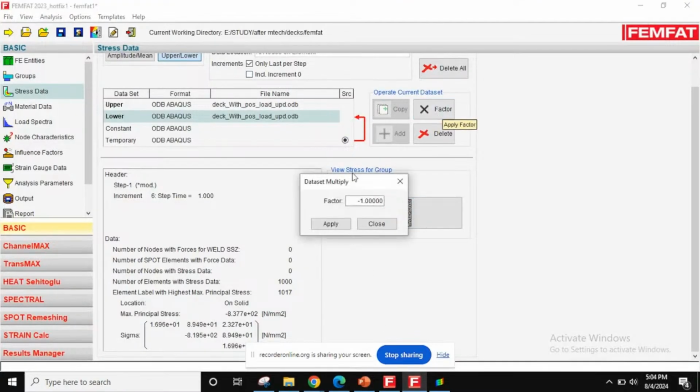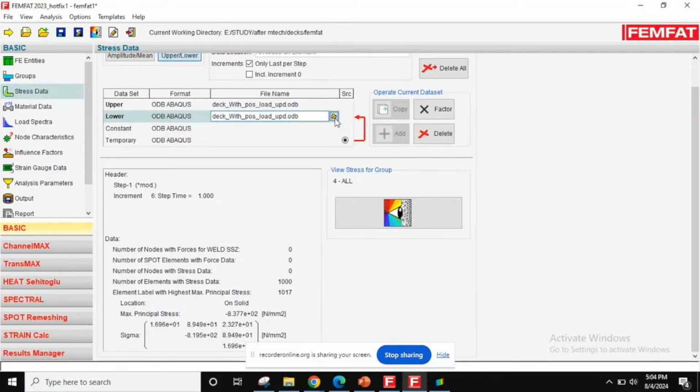You can't just use the factor again, as it will not scale the stresses correctly. So again, don't override the factor. I mean to say, if you want to replace the factor, again read the same stress. It will update it to the original, that is 837 MPa.